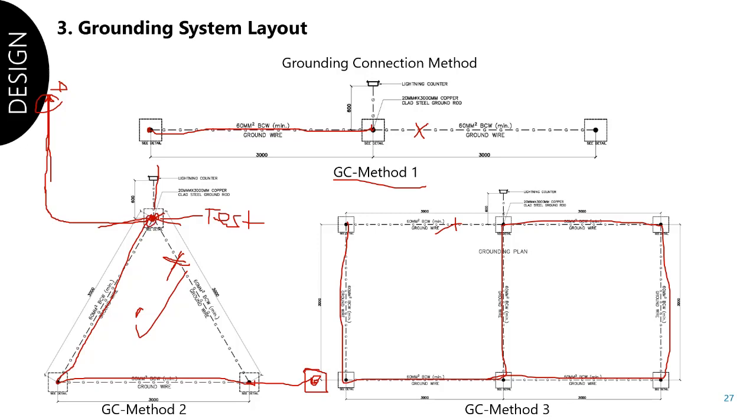So that's why we have a direct burial clamp, so that you can isolate and do the testing of the ground rod alone, not including the air terminal, or you will not be feeding voltage and current into your air terminal, even if it is a small radius. Of course, it would not be covered by your manufacturer if you damage the air terminal in the first place. So that's the main reason we have a test pit, to isolate.